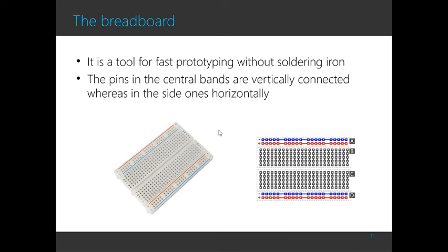How to develop an application in a way. If you don't want to use the soldering iron, you can simply use these breadboards, which are simply plastic tools in which inside the connections are on the same column for the central bands, because they are vertically connected, and also we have horizontal connections for power supply on the external bands.